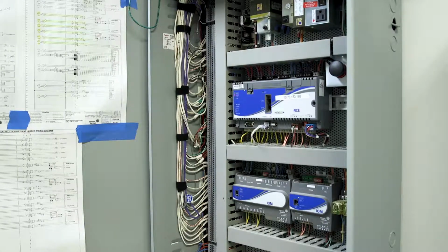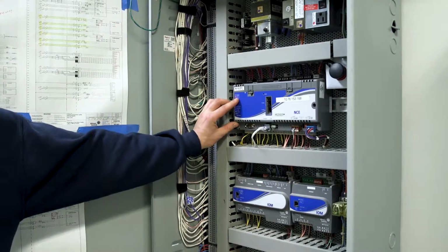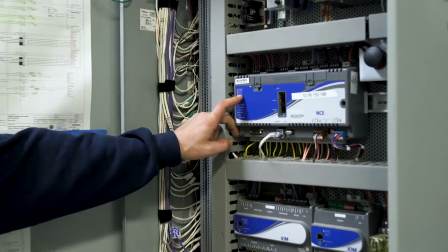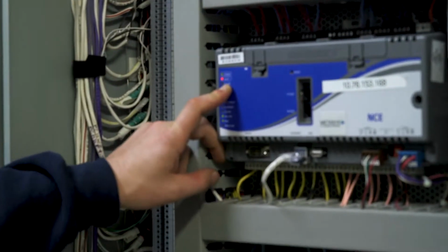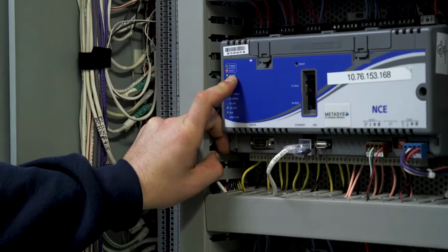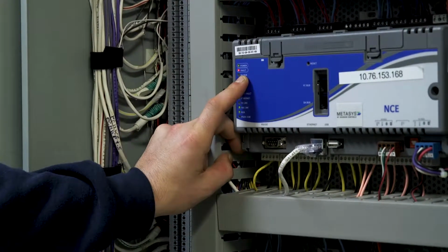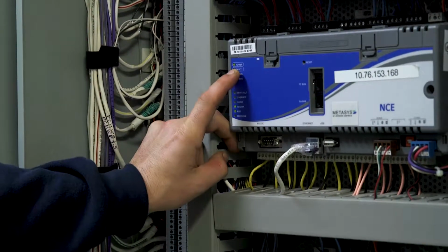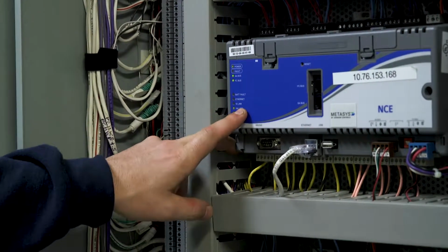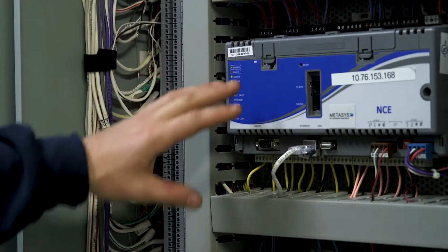And as far as these, well, on the NC you got these lights. The fault light, when you see a flashing fault light, it could be a bunch of different things. It could be internal board temp. It could be you're near the capacity of the memory in there. There's a couple different things. Just on this box itself, right?